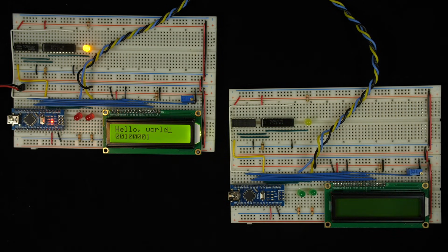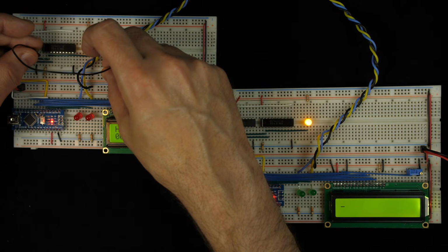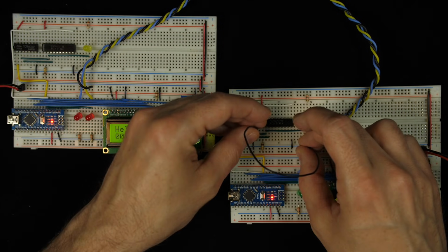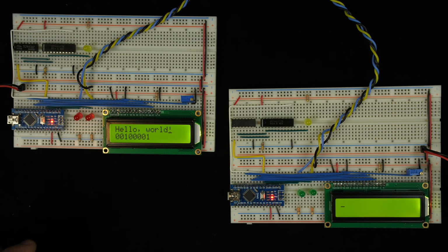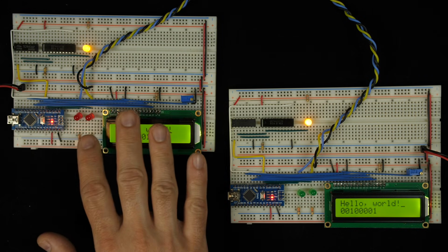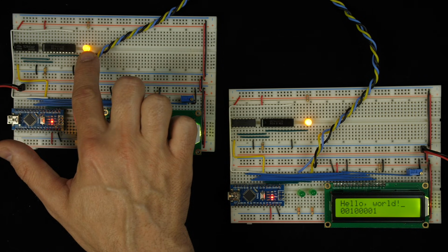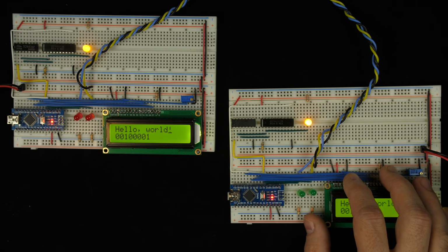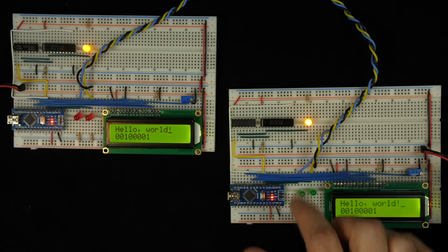All right, so now let's power up our receiver. And so this is where I want to be able to reset the parity bit. So I'll manually connect ground to pin 1, and that should reset it. So now if I reset the transmitter so it resends the message, we should see the parity getting computed on both ends. And if there are no errors, then it ought to compute the same parity. And indeed, it looks like it came to the same answer. So after sending the message over here, we've sent an odd number of 1s, and after receiving the message over here, we've received an odd number of 1s.